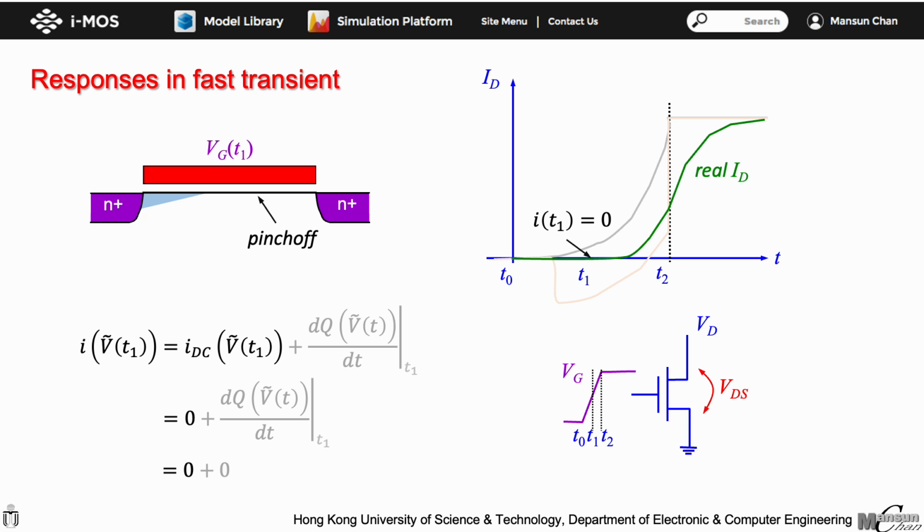From this example, we can see that the quasi-static assumption used in SPICE's equation to compute the source and drain current by the equilibrium current plus the charging current is inherently incorrect. The so-called DC current is dynamically changing with time and cannot be assumed to be static.